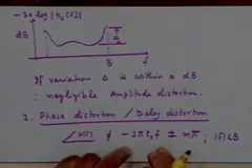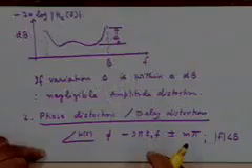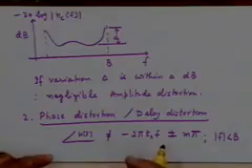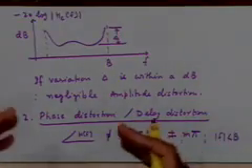If this is so, what is the amount of delay introduced at frequency f? t naught, right, and it's the same for all frequencies, right. If this is not so, basically what it implies is that different frequency components undergo different amounts of delay, and that's why when they combine together all these frequency components at the other end, the output signal does not appear to be the same as it started with, right.